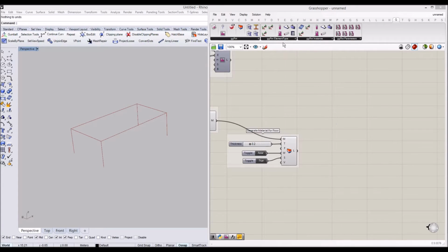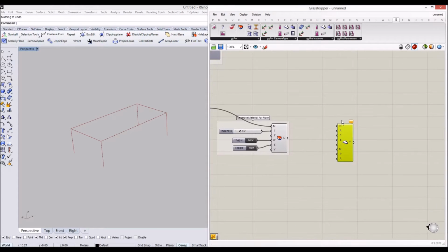Now we can apply our geometry to the floor. In order to do that, let's go to the next tab here, and I will use the Geometry Gym Floor Type component. We'll make the type parameter for Revit. So what I'll do here is use a panel again. In this case, I'll type concrete C20/25 floor as the type name, C20/25 floor type.